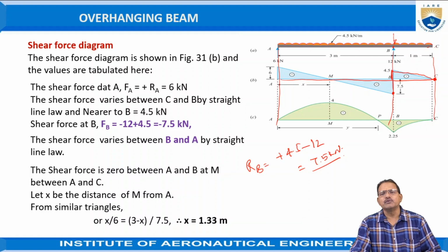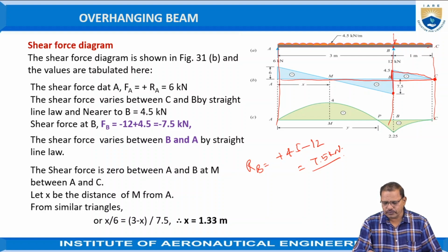While representing the forces, select a suitable scale. Here, according to this figure, I am taking 1 kilonewton equal to 5 mm.